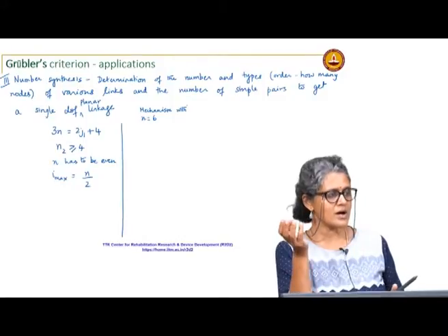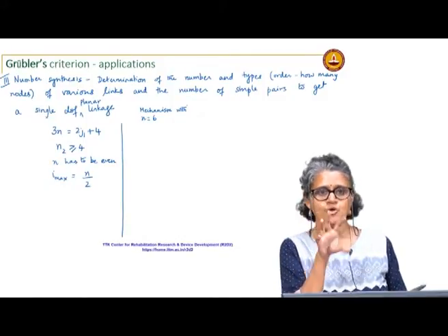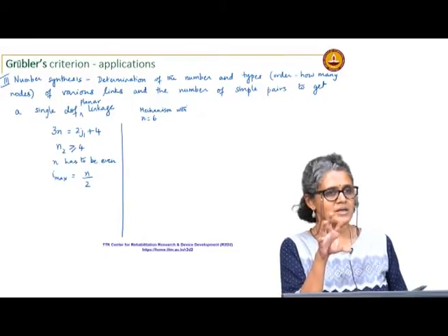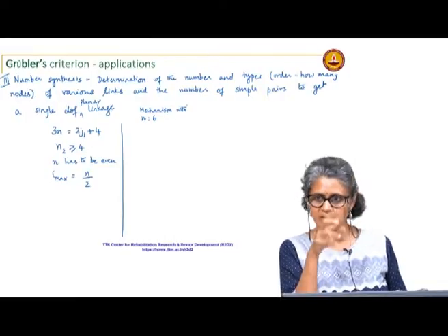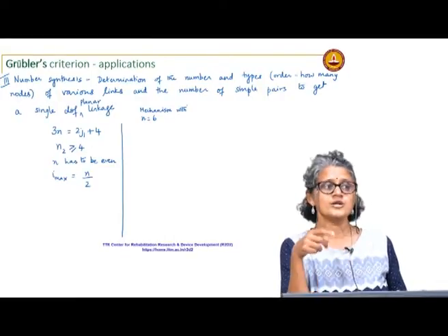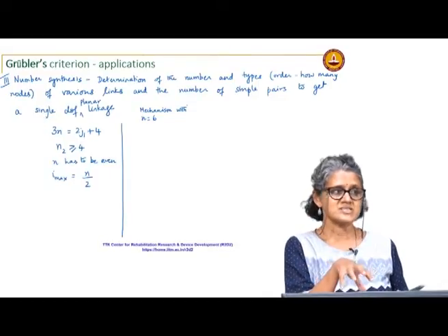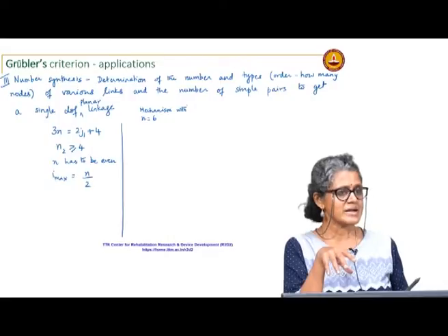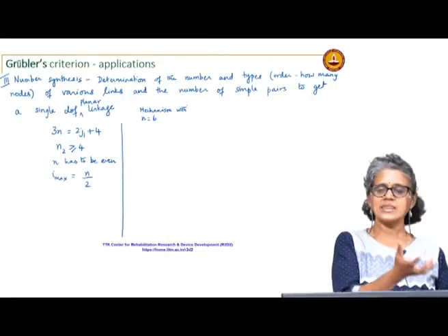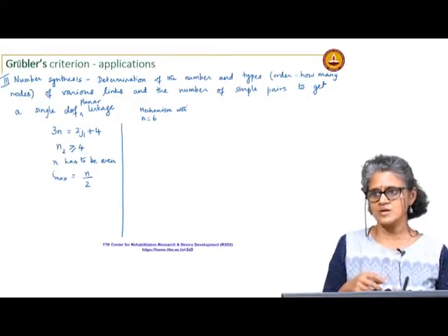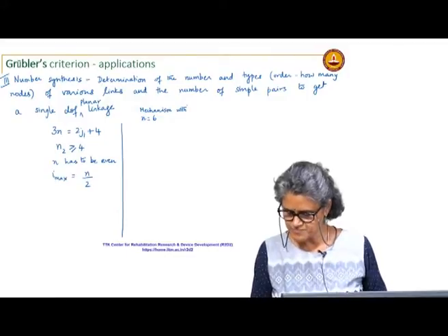Those of you who have seen before, sometimes if your 4 bar cannot do full rotations, you will need to add a couple more links and make it a 6 bar in order to be able to run it with a motor, etc. So, in many applications 6 bars are quite widely used. You may start off by designing the 4 bar and then make it a 6 bar in order to just even be able to run it with a continuous input.